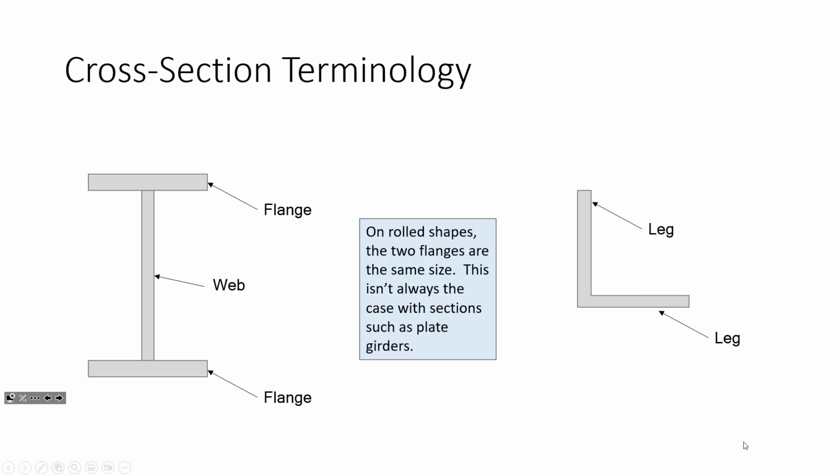That is very common in the land of bridge design, because what we find is that as we start placing load on the system, the compression flange and the tension flange see different effects. They also behave differently. Tension flanges like to yield and fracture. Compression flanges like to buckle. Different mechanics means different sizes, but plate girders are tailored to their load demand. For building design, we can just use one of the commonly available rolled products, so both of the flanges are the same size.